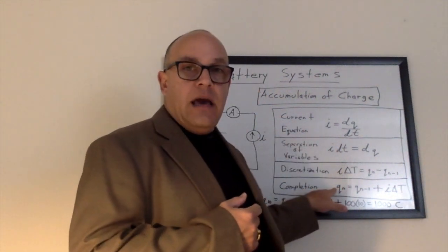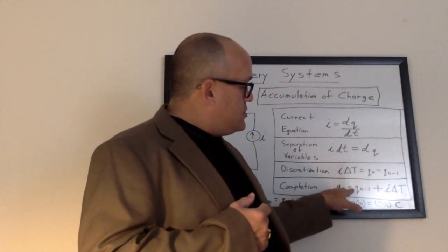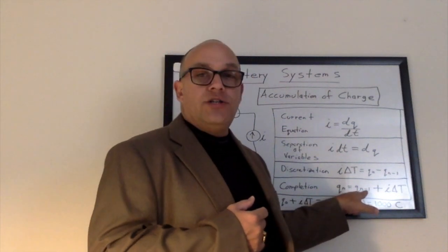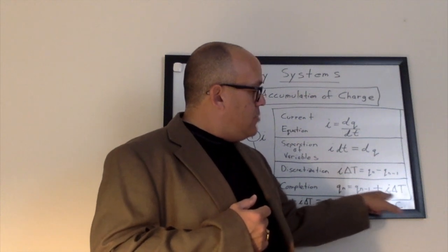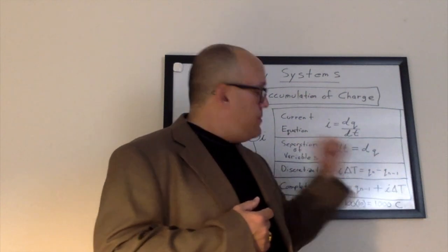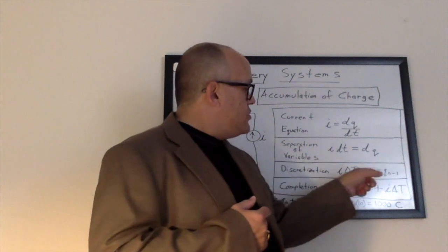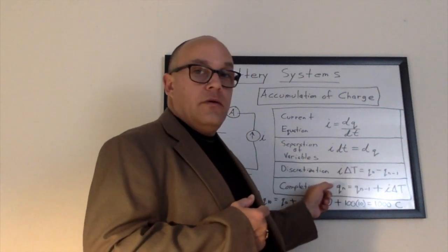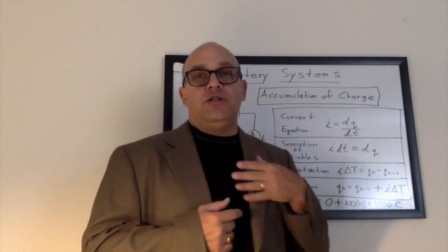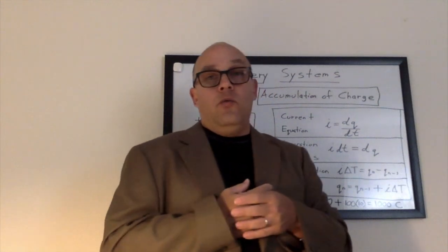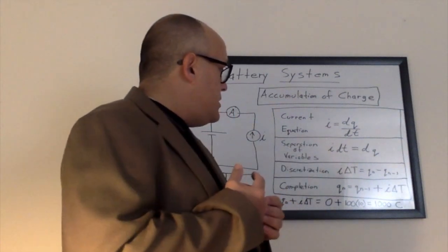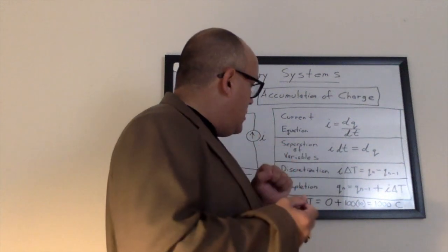The charge at time n equals the charge at time n minus 1 plus the current multiplied times the time interval, delta t. We just rearrange this equation and get this. You can plug this into a spreadsheet or a computer algorithm for control systems, battery management systems, BMS, or whatever you want. This works, and that's the actual physics equation converted to a discretization formula.